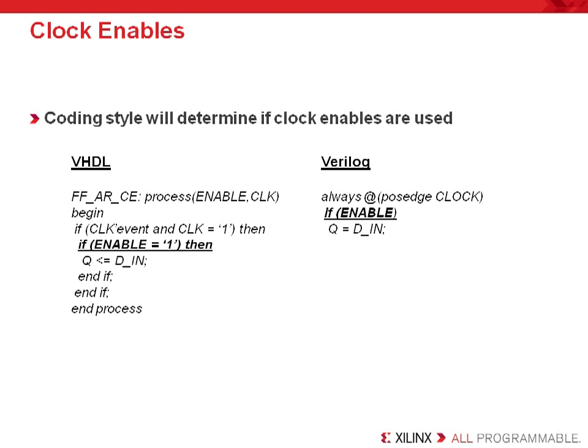Clock enables are used in synchronous design. They should always be used instead of gating a clock. As you know, gating a clock signal and then driving it to a clock port on a flip-flop can glitch in any FPGA. To synchronize the clock, just drive the derived clock signal to the clock enable port. In these examples, we see the clock enable as a simple 1-bit signal, but it could be whatever derived signal you want it to be. The key is that the enable